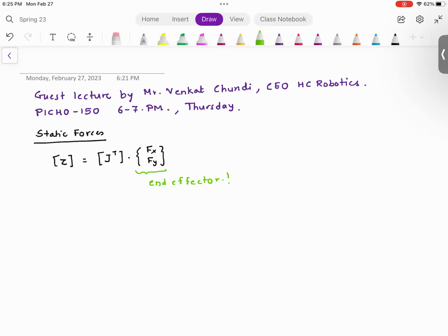Many times the robot dynamics is non-linear, but the techniques that are known to solve the problem in closed form are all linear. So somehow we have to take this non-linear dynamics and linearize it. In other words, do a Taylor series or Jacobian, something like that. So this non-linear dynamical system of equations is converted into a linear equation.